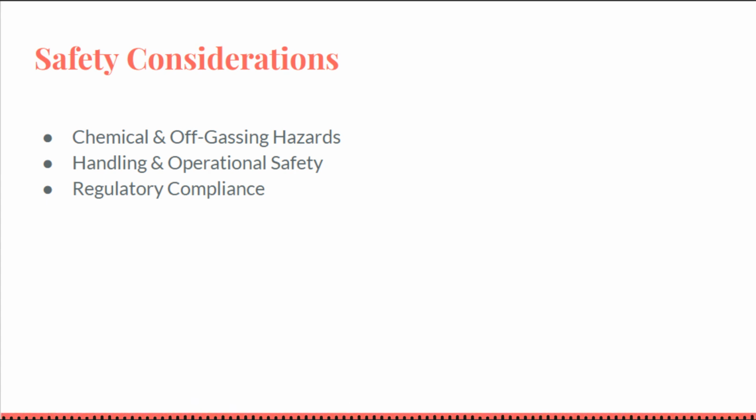Always shut off power before servicing an ozone or AOP unit. For ozone units, avoid touching the corona discharge element as it can be hot and is high voltage when operating. All ozone systems should include check valves to prevent water backflow into the electrical generator. Failure to install these can create an electrocution or equipment damage hazard. As with any pool equipment, components should be UL listed or equivalent. Fluidra CMP's products, for example, are NSF 50 certified and designed to meet safety standards.